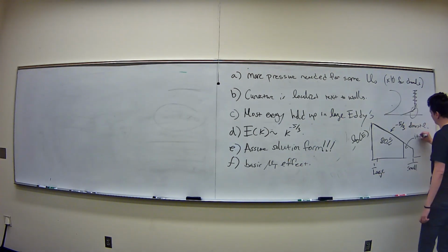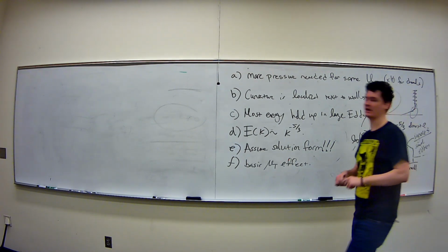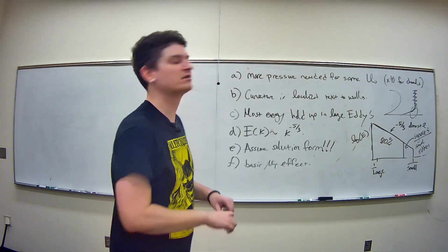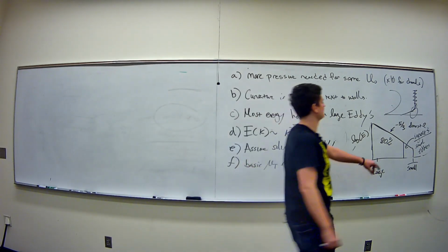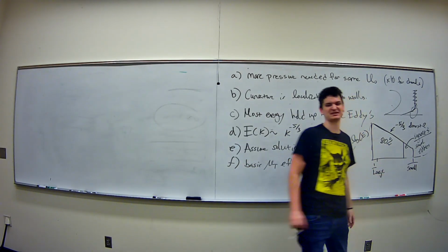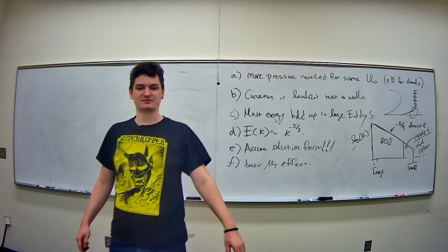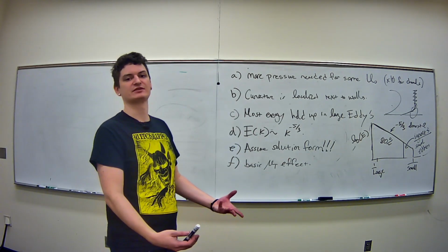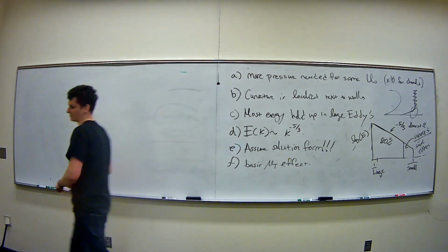Where here it ignores small eddies, usually about 80%. Okay, so on a large LES simulation, it does this trickery where it has grid sizes locally that can only resolve so large an eddy size, and it has a filter function on that average, and numerical analysis gets you here, and then you really shoot for this 80%. And there are models for implementing the Reynolds average equations. There's K epsilon models. There are models that essentially look at those average equations and come up with more equations to solve them. Okay, so closure problems.